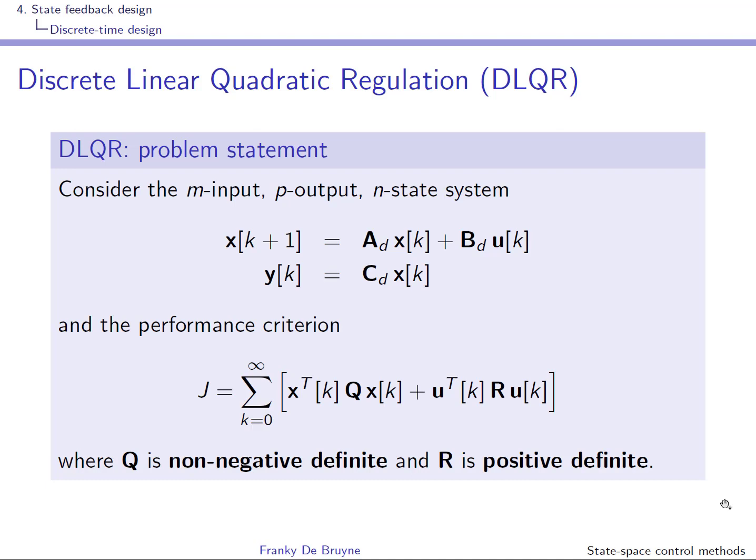It is of course possible to implement a discrete time LQR design, a discrete linear quadratic regulator, and without surprise, the Matlab command is DLQR, right? You start from a discrete time state space description of the system obtained after discretization of the original system with the ZOH method to take into account the effect of the zero order holds.